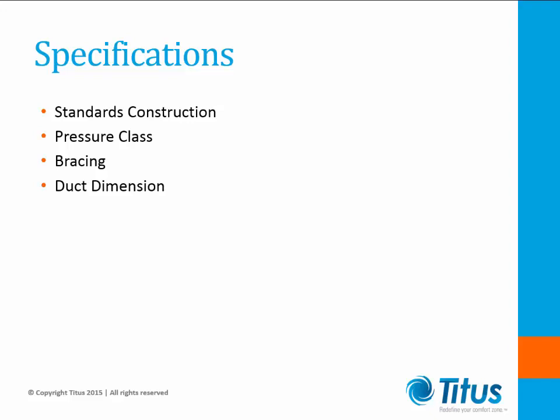Duct dimensions on drawings should be detailed, as to how they are designated on the drawings. In most designs, the ductwork sizing on drawings are inside clear dimensions and do not account for liner or bracing. This should be clearly identified either in the specifications or the drawings. This will allow contractors to provide accurate pricing for the project and ensure the design intent of the project is met.